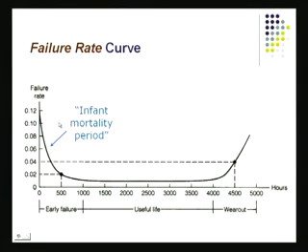And this is a small period of time. A few products die there, and these are generally because of manufacturing problems. Those sneak in, they get into the packaged stuff, and you end up with these products when you take them home. There is a cure for this, and that is done by doing a burn-in before the product is shipped. So the failure rate is pretty high early on, and this is the infant mortality stage.